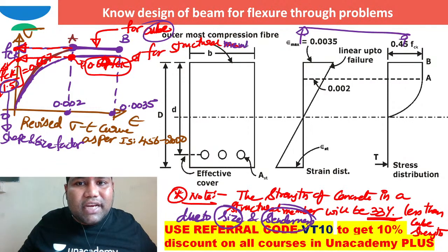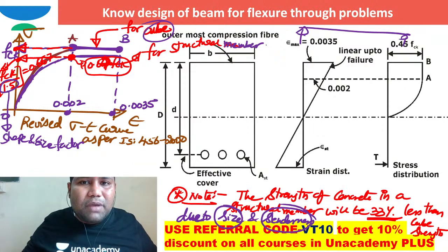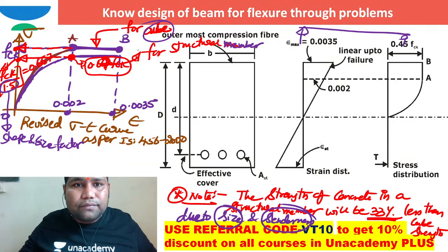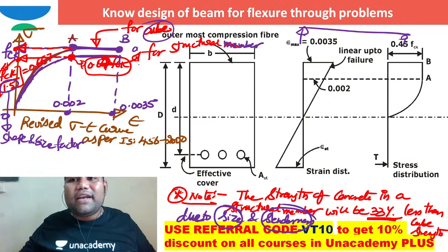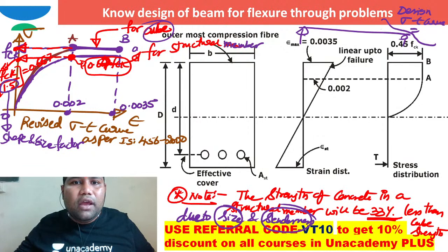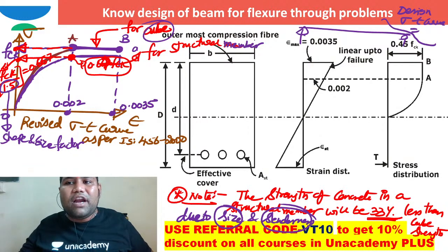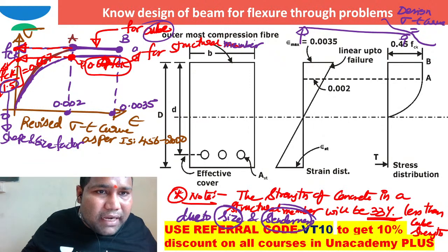Okay, this is the stress strain curve for structural member, but I need to use the design stress strain curve. This is the actual stress strain curve, or rather the ideal stress strain curve for structural member. But I want the design stress strain curve. How will you get the design stress strain curve? The design stress strain curve is equal to the actual stress strain curve of the structural member divided by the factor of safety of the material. What is the factor of safety for the material of concrete?